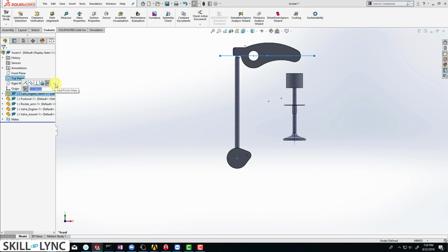So now if you try to rotate this, you can see that it rotates perfectly. Now what we want to do is set the system up with the right amount of contact. So we are going to have a small gap first, and then go to assembly and then go to move component, and we are going to use something called physical dynamics.